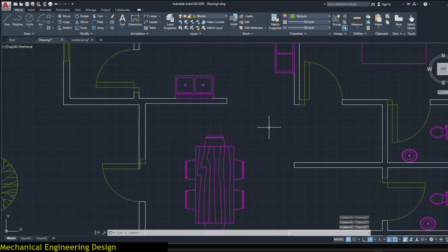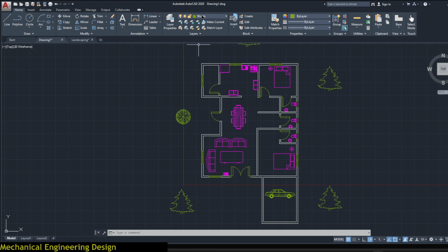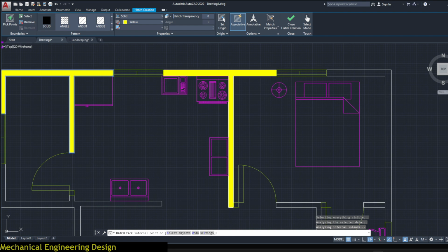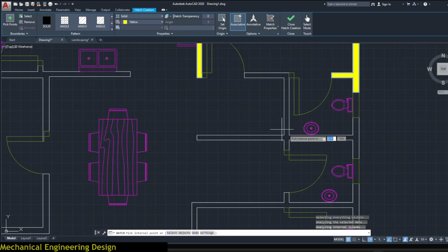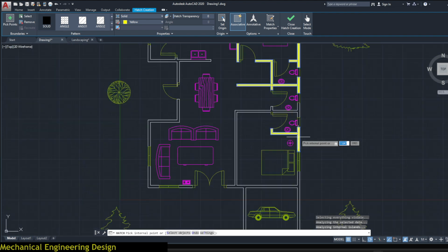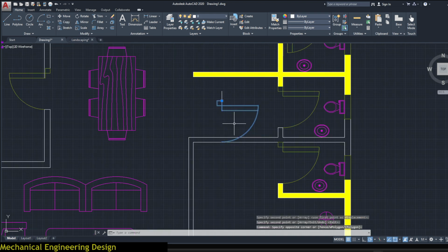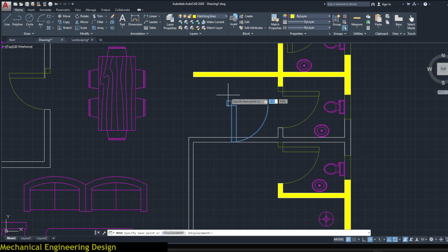Now see what we have. We need to do the hatching. So we change the layer to hatching. Come to hatch. Now we still have a door to place here. So we can copy this one, rotate, and then we mirror like this. Now move, select this corner, come to this corner and drag it horizontally.